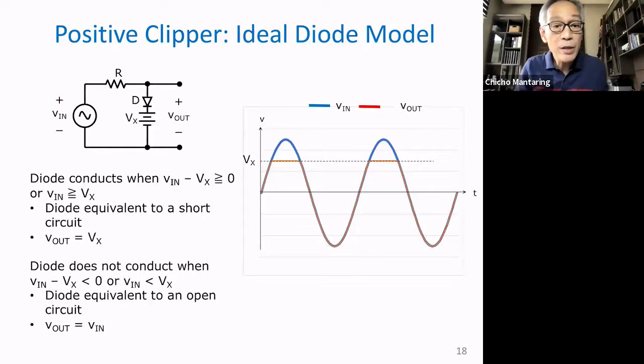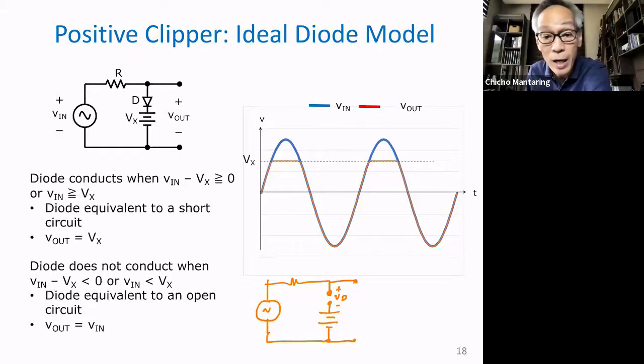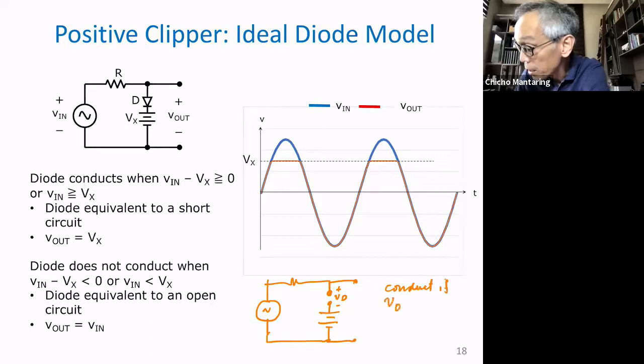Okay, when does the diode conduct? No? Again, no, how do we determine whether the diode is conducting or not conducting? Well, let's use method 2 again. No? So you replace it with an open circuit. So open yan. Okay. So this is plus minus VD. Okay. When does the diode conduct? The diode will conduct if VD is greater than or equal to VF.